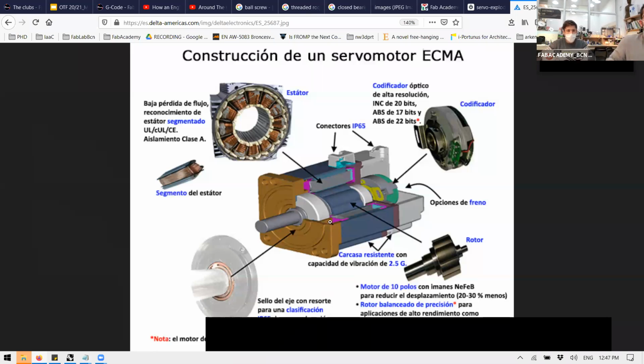So basically, it's like a stepper motor. How it's built inside could be similar to a stepper motor, but it's more complex. It's closer to a brushless, and has an encoder to read the position plus electronics. And usually, as they are industrial grade and more complex, it also means better build quality, better bearings, seals. In general, as you go to more expensive hardware, they already assume that you need some minimum industrial quality, and they are really good quality.